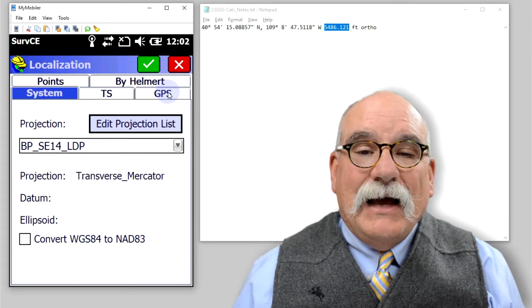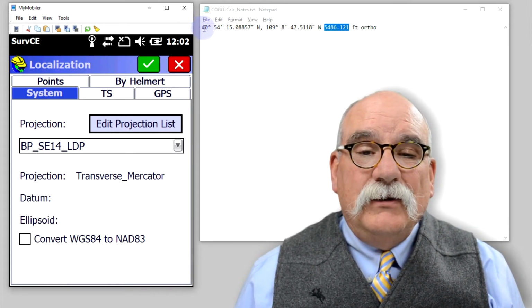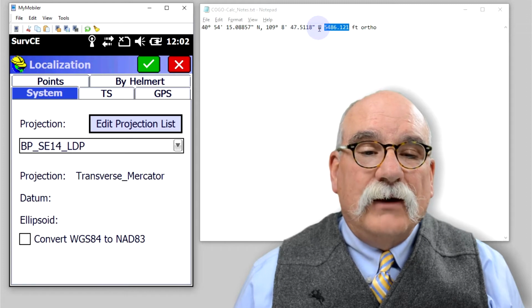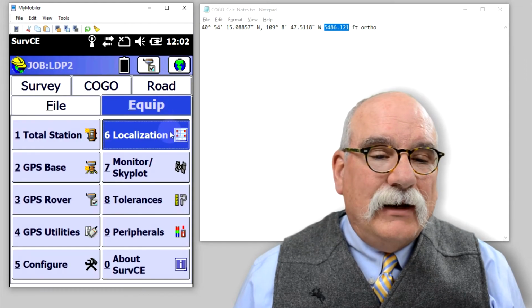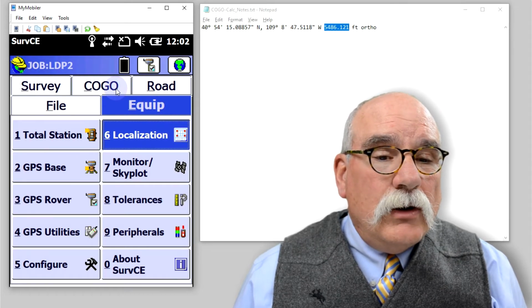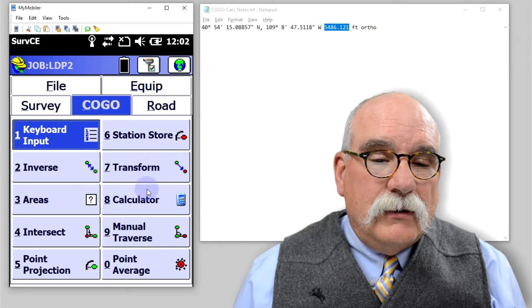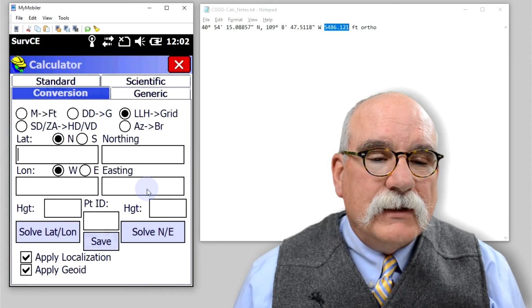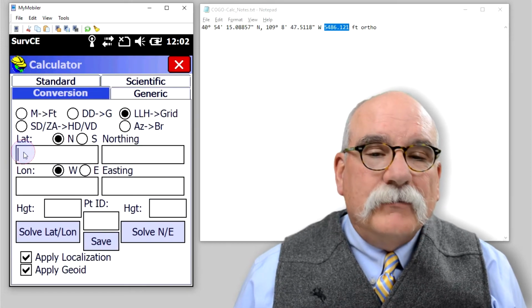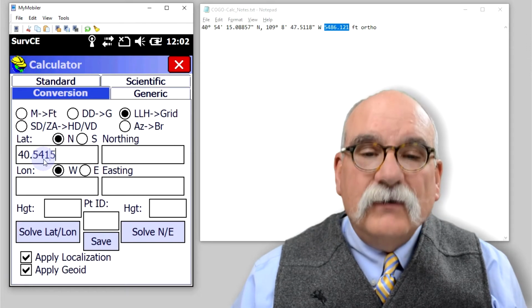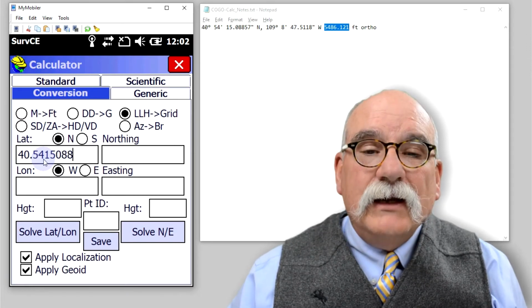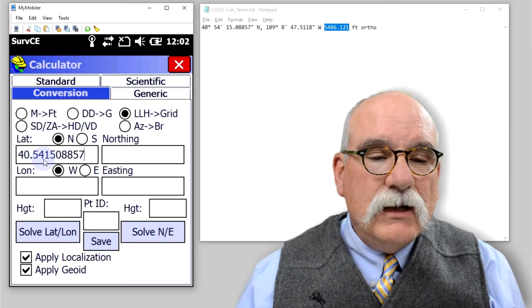Now, I don't have LDP coordinates for this latitude and longitude. But the point of this video is to show you it's not a big deal. If we go to COGO and then calculator, we can just type them in. So let's type in 40 degrees, 54 minutes, 15.08857 seconds.